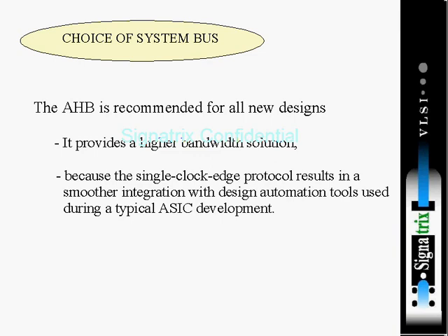But can this AHB be used for event based also? We can use AHB for event based simulation also. No, it's not like that. We can use it in event based simulator also, but in ASIC development, since it is operating with reference to clock edge, single clock edge handover and single clock edge operation, it will make our life easier in ASIC development. That's it.